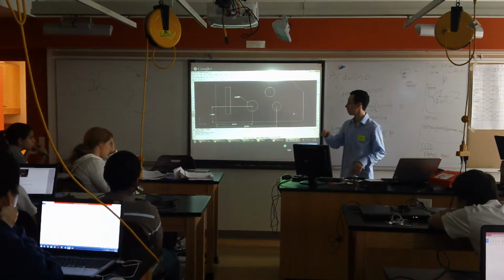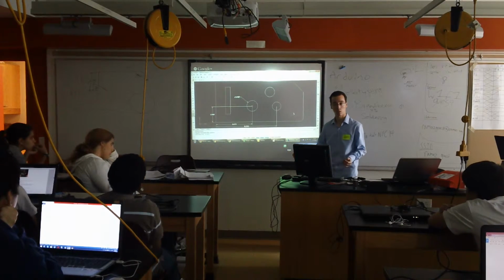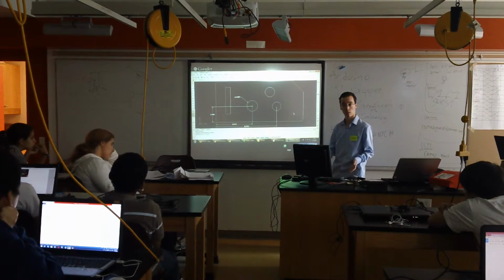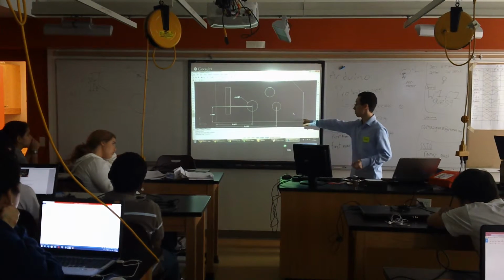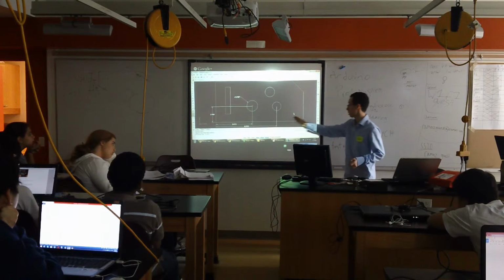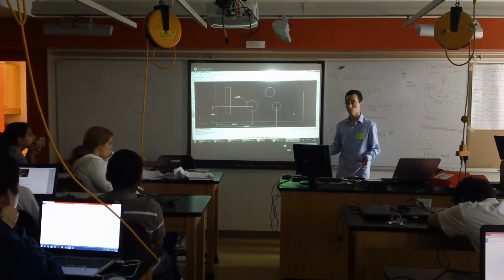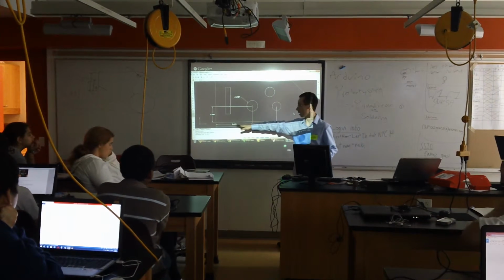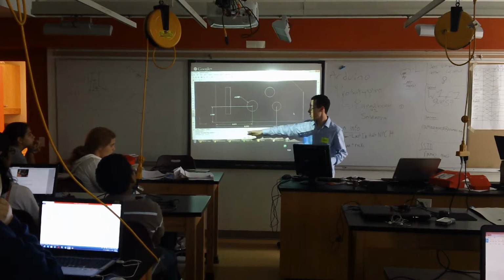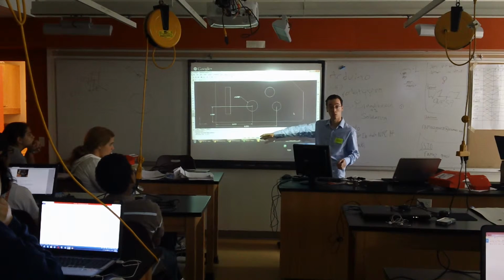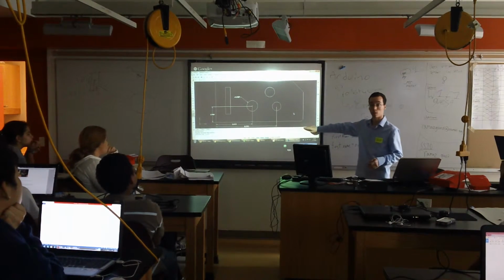Okay, good, great. So I could repeat this process for the other two circles, and you understand how that would work, right? How that would show me exactly where these would be. And if I did the same thing for this radius, now I would know the length of this, this chamfer, and so on. And you can see how the convention is to stack dimensions like this to make them easily readable. Or if you're doing chain dimensions, for them to all be in the same line like this.